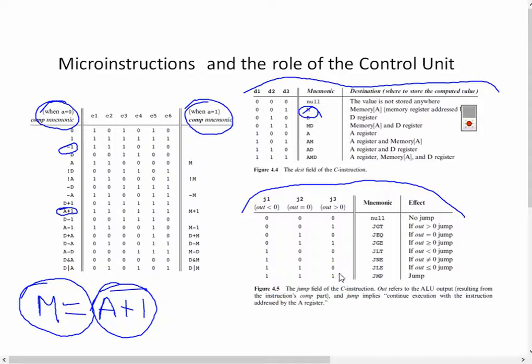So clock ticks, goes to the next program counter, the program counter then loads the next instruction into the ALU, and then it does the computation. Then the result is going to be stored wherever we specify by the destination. Now, the jump basically gives me an ability to define under what cases and what conditions I might want to move to a different line within the code. I have a number of different possibilities from a jump perspective. Essentially what all of them are saying is that I keep track of, or I should say the ALU keeps track of, the outcome of an operation.